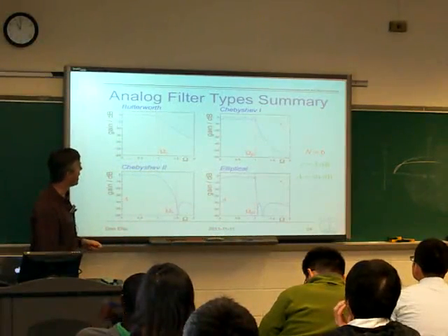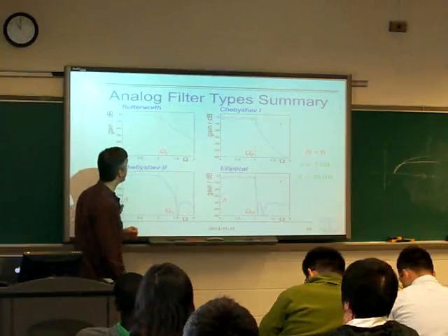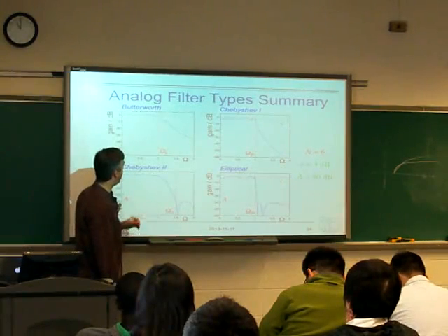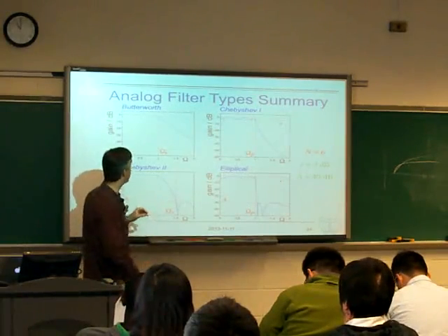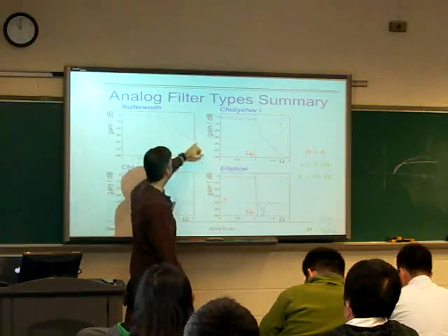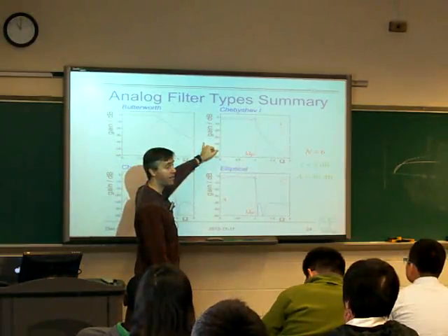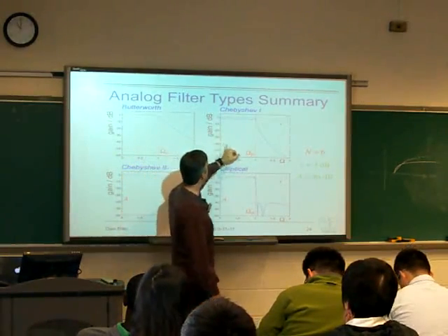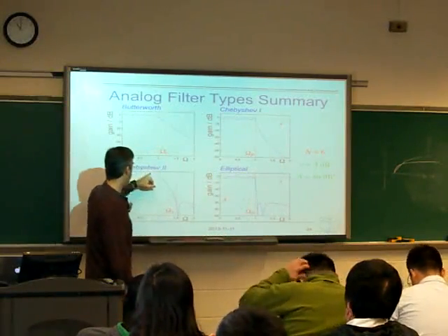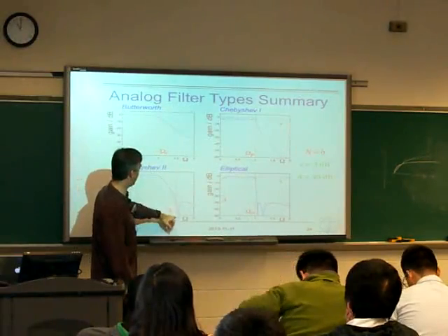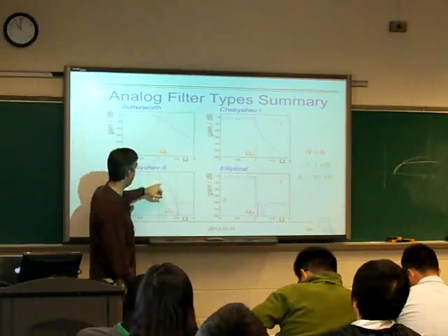And you can see that, using equivalent constraints, the performance gets better. In this case, the thing we haven't limited is the transition bandwidth. So here, this thing gets down to 40 dB at like 2.3 times the passband edge. This one gets to it at like 1.4 times. This one actually is sort of about the same. It's 1.5, and maybe the gain is a little better than 3 dB here.